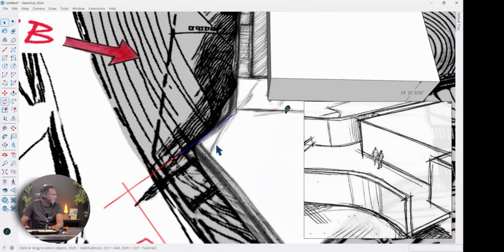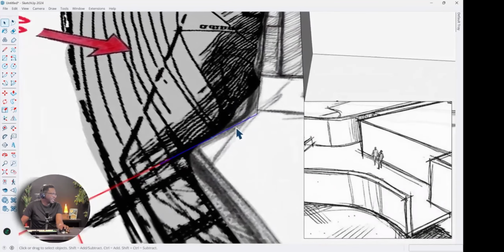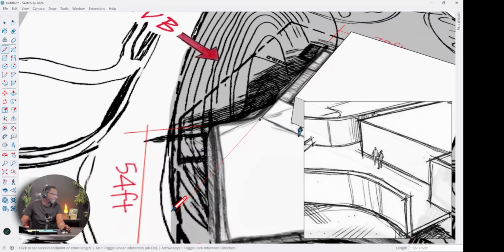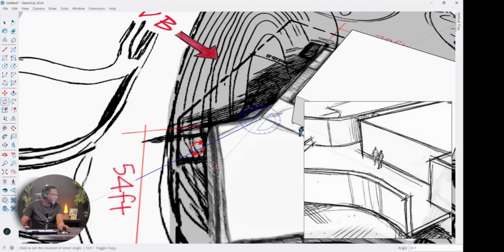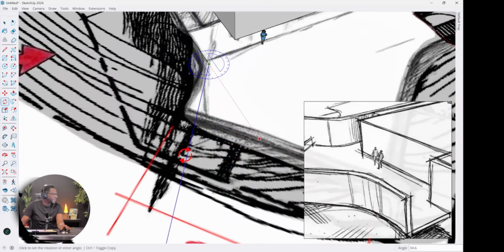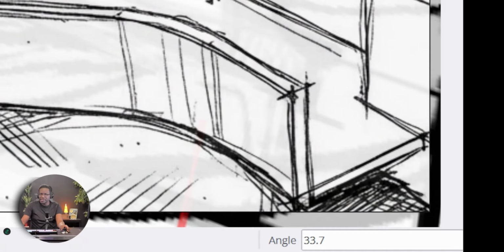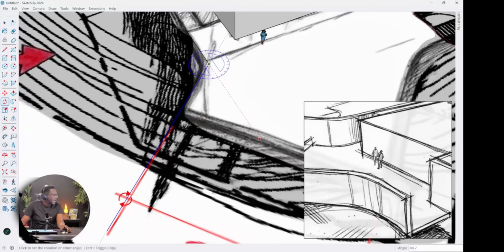All right. Now, usually when I'm sketching, I like to work with even numbers. So the best way to do that is, let's delete that line. I'm going to put a line here. I'm just going to make it any length. That's fine. So this is that line. I'm going to use my rotate tool, and I'm actually going to rotate this. But when I use my rotate tool this way, it snaps to different angles. Now you can see the angles down here that it's snapping to. When I move, I can see what's happening down there. All right, so I want to move this to the closest point, and I see that it's close to maybe 50. So I'm going to type 50 and press enter.